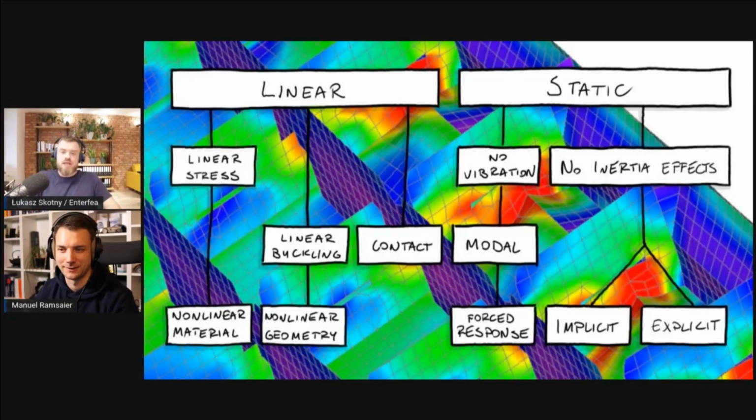Yes. And then the modal analysis would be a perfect equivalent to linear buckling analysis. It doesn't solve anything really, it just shows you things. So what I mean by this is that modal analysis will show you the frequency and what shakes and how big a percentage of the mass of whatever you have modeled shakes.